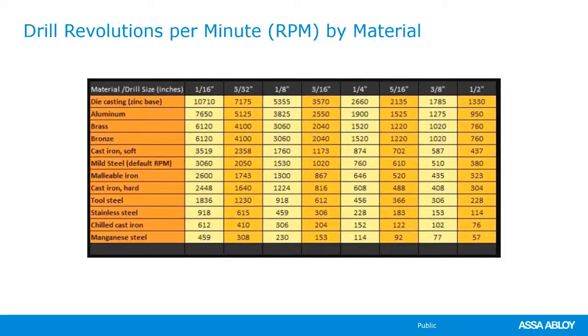And with everything, if you work with technicians and they're always burning up drill bits, more than likely it's because, well, they may not be using a quality bit, but more than likely it's because they're using a full trigger pull on their drill.